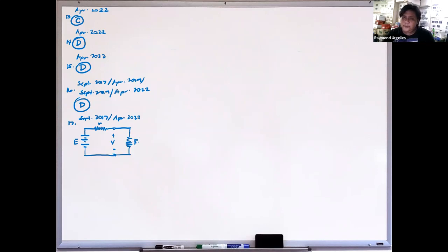Okay. So that will be the load. So to solve for the internal resistance, it is given by the internal EMF minus the terminal voltage, based on the given. What we lack is the current passing through here, so let's say it is I. So this is divided by the current I. But instead of the current, what is given in the problem is the power taken by the resistor load. So therefore, our current is just given by power divided by the terminal voltage. Nakuha ba? So our solution here will be 15 volts.